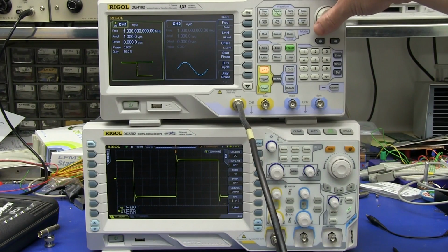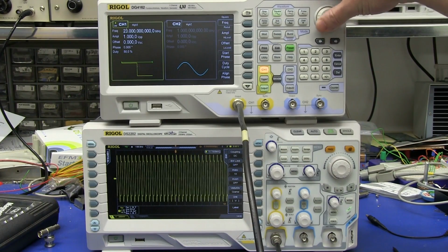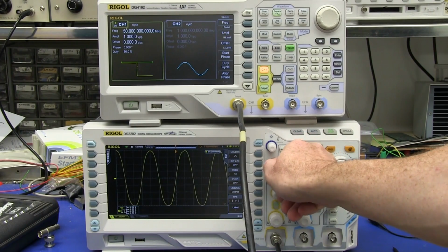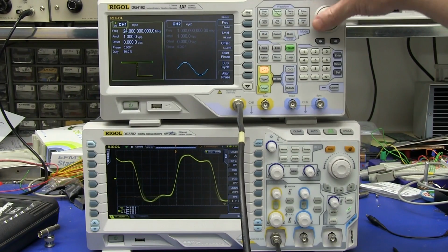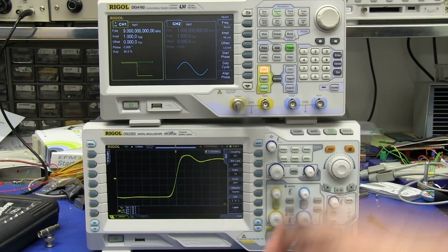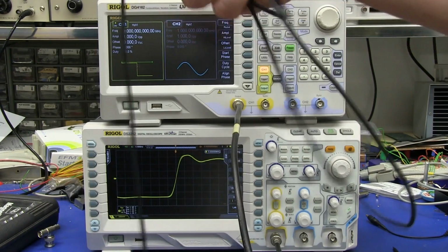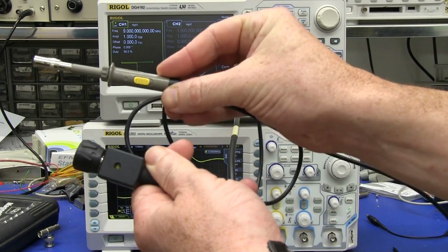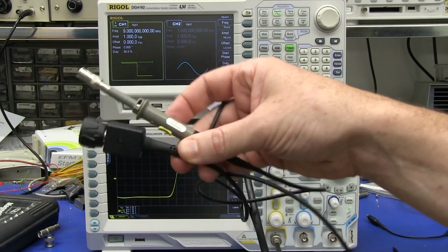But let's increase this in frequency. We're at 1 megahertz there. So let's wind it up. And as you can see, 40 megahertz, 50 megahertz, no problem. It's rounding off there, but there is no attenuation of that signal by just a bit of coax. So why does your humble oscilloscope probe have a lousy, barely 10 megahertz bandwidth on ×1 mode when it's supposed to be just switched directly through?